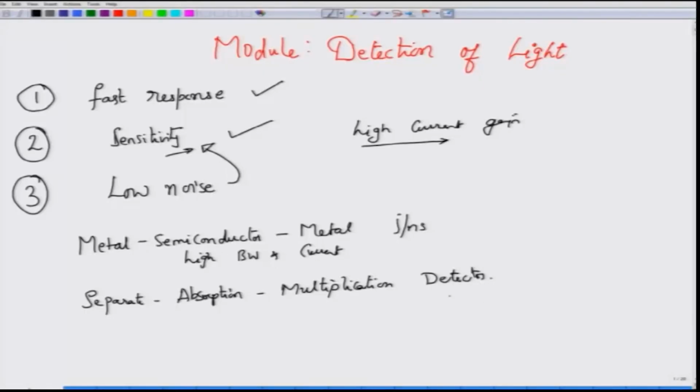In a more general sense, this characteristic is called a photomultiplier, and photomultipliers are also used in the visible range of optical communication. But when it comes to optical fiber communications where the frequencies are in the infrared, mid infrared, you will be using semiconductor photodetectors. The commonly used SAM photodetectors, the separate absorption multiplication photodetectors, are made out of indium gallium arsenide and indium phosphide heterostructures.